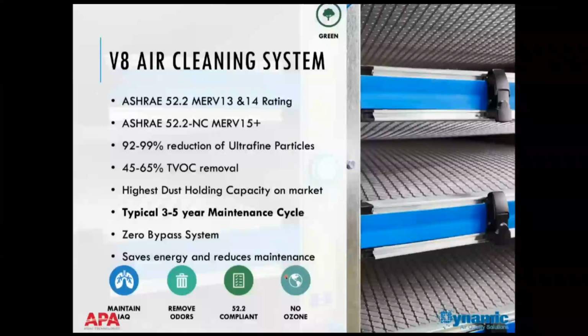Another important element is that it is an engineered system that is built to the specifics of a given air handler cross section, so there's zero bypass around the filters, which is a critical part for any filtration, right? If I've got HEPA filters and I have a gap this big between them, I don't have HEPA filters, and so filter seal is critical.